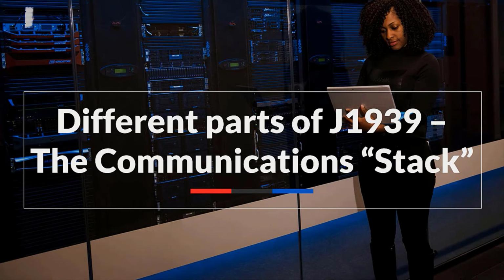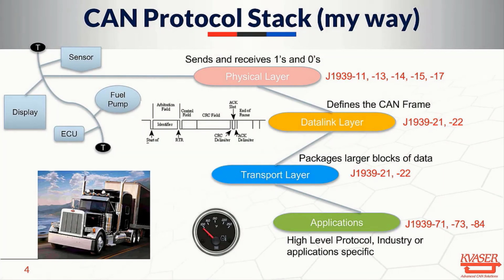And the different parts of the J1939 communication stack, as it's called. This was covered in CAN Basics, which is a prerequisite for this particular training, and I hope that you all have that. It makes a lot more sense. A similar slide to this was used in CAN Basics. It shows a typical CAN network here, which has 4 devices on it. There can be quite a few more than that. It shows that it is the physical layer that sends the 1s and 0s reliably across this network and handles all of that. That covers the voltages, the impedances, things that dictate physical layer transmission on this network. The specification that dictates the physical layer we're going to be working with today is the J1939-11 specification.